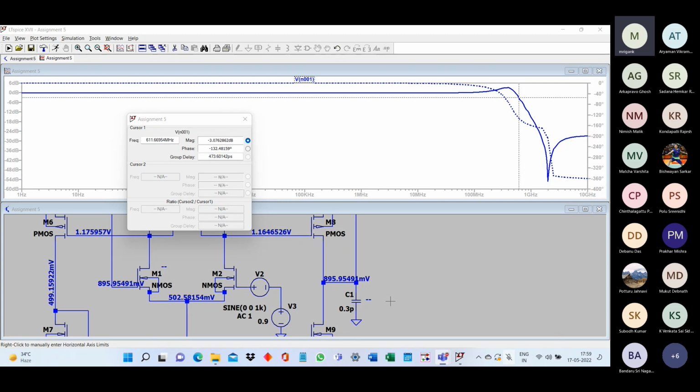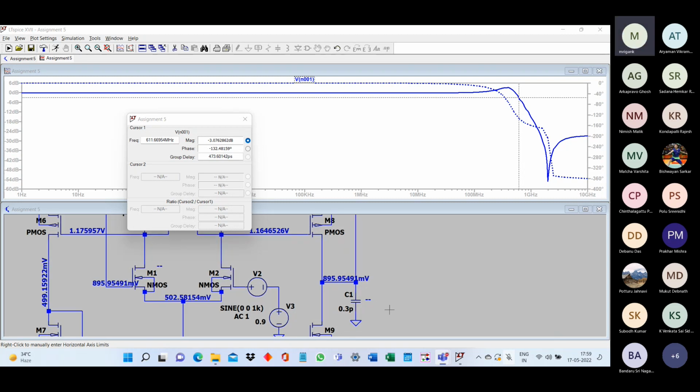Right now, if you look at the overall phase margin, it is also reduced to 35 degree. If you increase the capacitance, that will become flatter, because the zero will be further; the lower the dominant pole, the less will be the effect of all these zeros in the response.